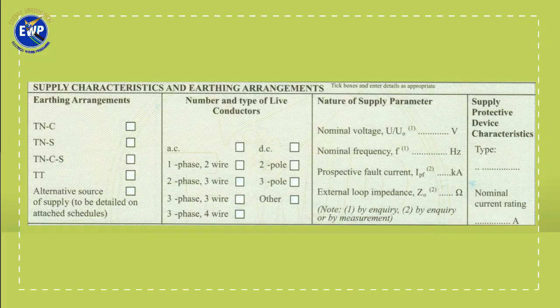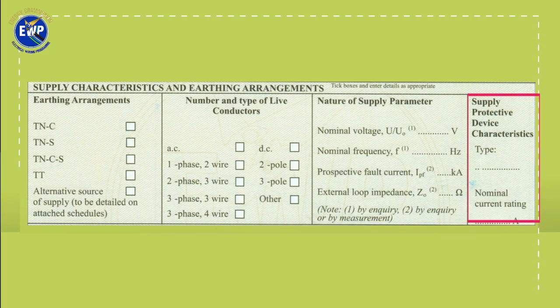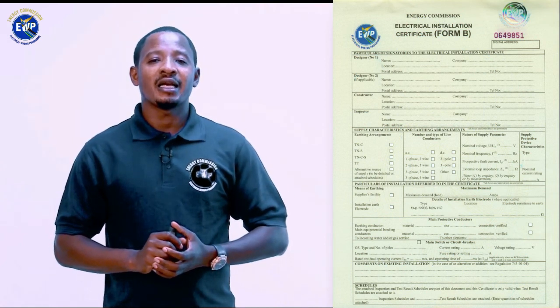Now, it is the details of the service cutout or the MCB that you are expected to write here. The type can be either a fuse or an MCB, and then you are to write the rating of the device. It can be 80 amps, 63 amps, 100 amps, or whatever, depending on the size of the system. Now, the supply protective device characteristics. You are required to state the type and then the nominal current rating of the device. The type is normally stated on the device. So let's say, for instance, if it is an MCB, the type will be written.